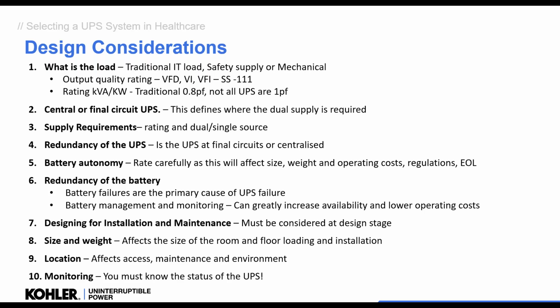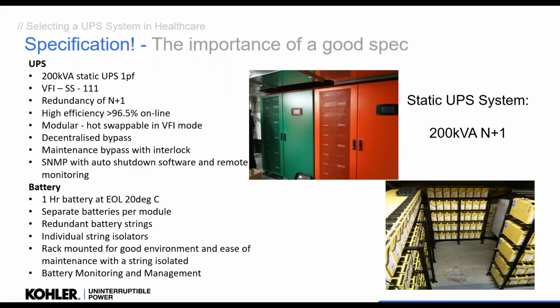It's surprising how many people just don't even check the UPS is there. A lot of this comes down to specification. We need to specify exactly what we want: the load, the power factor, the output, redundancy, efficiency, very important nowadays with sustainability, modular, decentralized, manual bypass, software and remote monitoring, and very specifics around the battery.